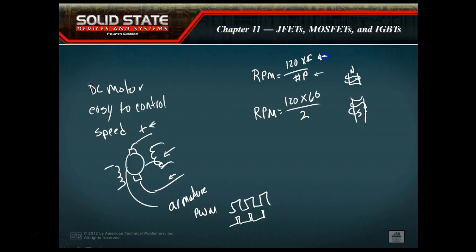The problem we have is trying to vary it with frequency. This is something we can vary electronically. If I change the frequency, if I make the frequency go up, it would appear that the motor will run faster. If I make the frequency go down, it appears that the motor will run slower. But the problem is we have something we call X of L. This would be the X of L of the motor, which means 2 pi FL.